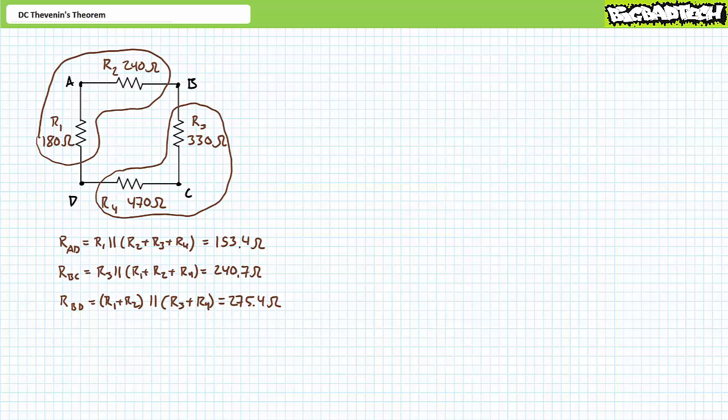The point is, resistance measurements of this seemingly simple circuit are like trying to nail jello to a tree if you consider different perspectives. This is the biggest stumbling block I've witnessed for students first learning Thevenin's theorem, and I'm asking you to keep this in mind when putting it to use. Observed electrical properties depend upon your perspective, and Thevenin's theorem shifts perspective from the source to the electrical load and back again. Throughout the course of the DC circuit analysis playlist, you'll notice that I've regularly drawn sources on the left and electrical loads on the right, only very rarely switching it up now and then.